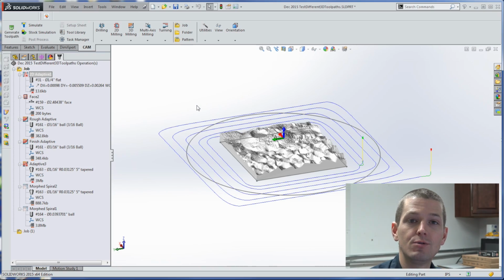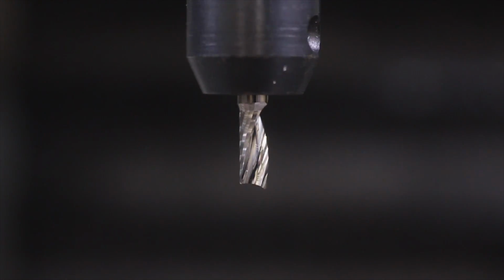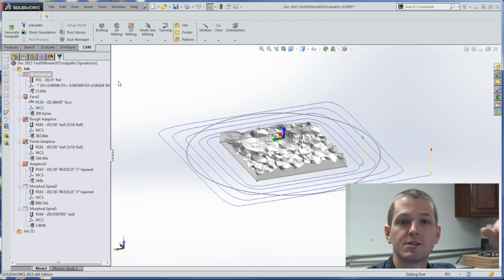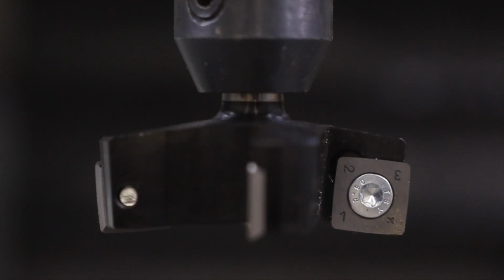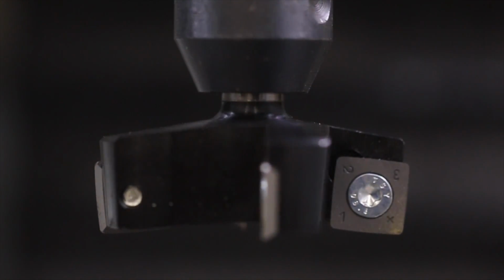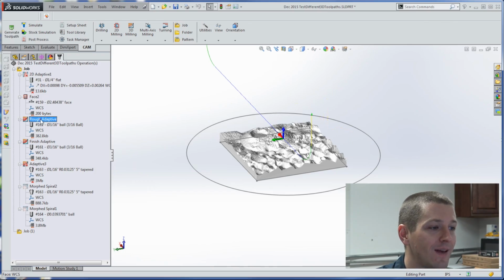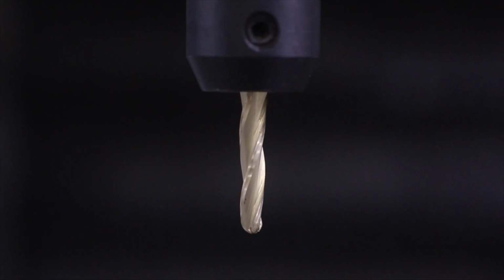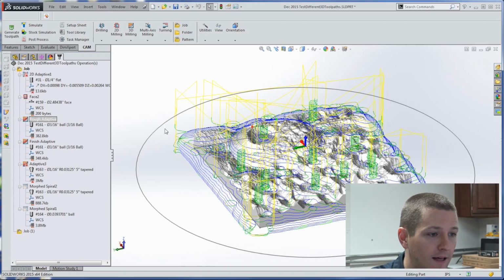To start out, we'll use tool number 51402 from Tools Today. It's a single flute 1/4 inch end mill. We'll use that to just rough out the stock around the piece of brass we've got. And then we'll use RC 3400, a 4 flute, about 2.5 inch face mill. It'll give us a really nice finish over the top of the part. And then we're going to come in with a 3/16 inch ball end mill, and here you can see we can really hog out a lot of material.